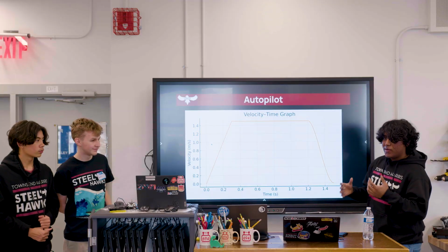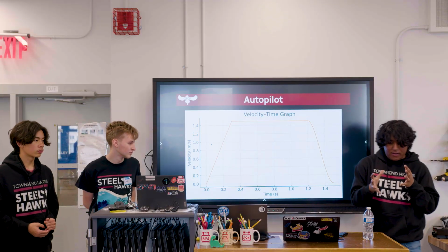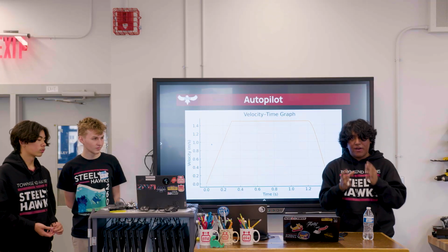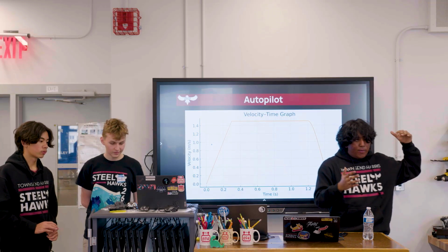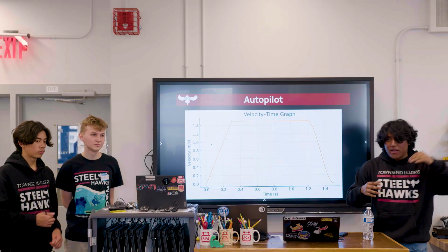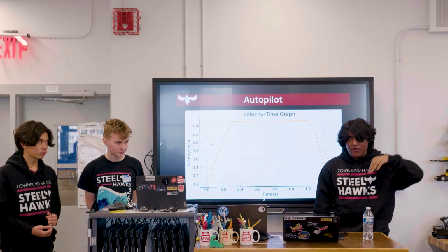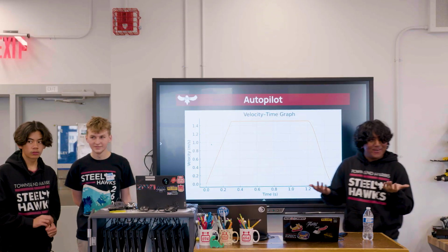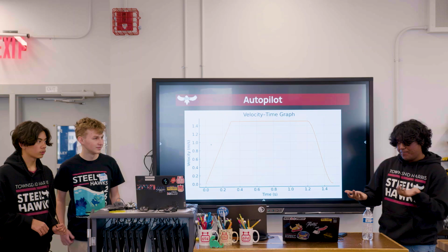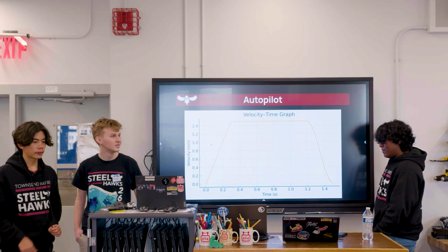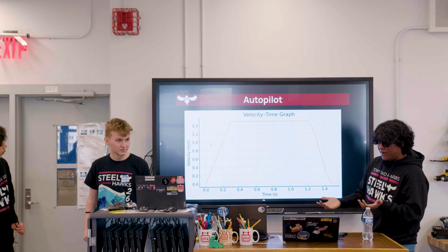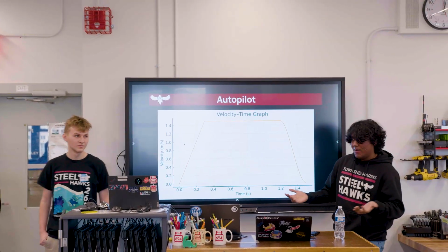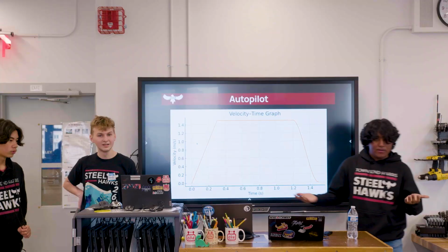The reason why you use an S curve is because it's a lot lighter on your mechanism, and we only use that for our drivetrain because what we would see is our robot would just slam into the reef. So we wanted to decelerate slowly, so we lightly love tap the reef. It helps with the slamming issue. We could have probably just set our set point a little bit further back, but this was also a very novel solution we found to an issue.